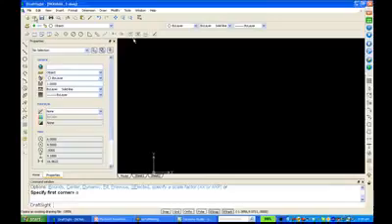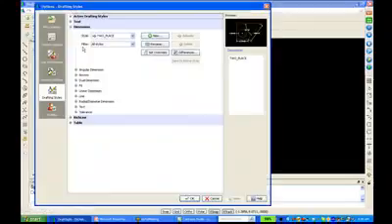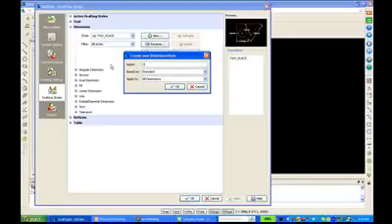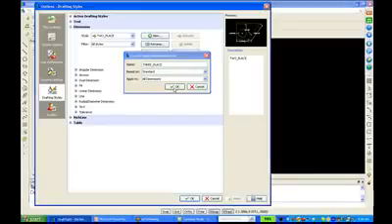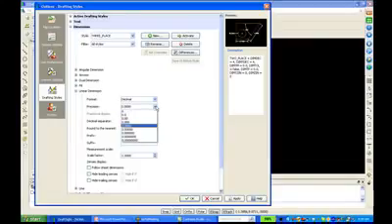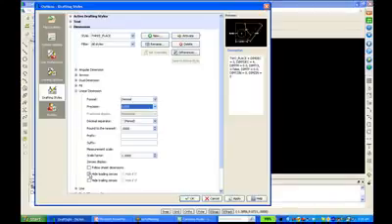Okay, I'm going to create another one, and I'll create one with 3 places. Dimension style. Create a new, but now I'm going to base it again on the standard, and I'll call it 3 places. And I can go to my linear dimension, 3 places, hide my leading zeros, click OK.